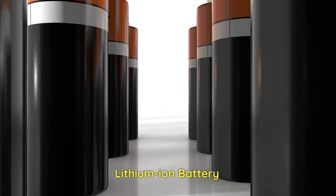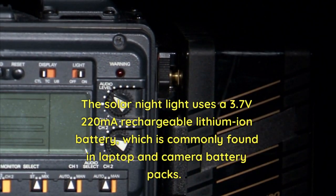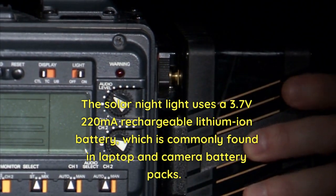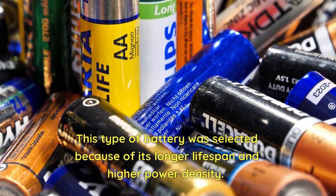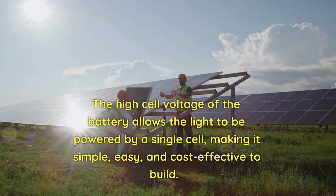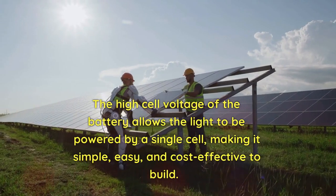Lithium-ion battery. The solar night light uses a 3.7 V, 220 mAh rechargeable lithium-ion battery, which is commonly found in laptop and camera battery packs. This type of battery was selected because of its longer lifespan and higher power density. The high cell voltage of the battery allows the light to be powered by a single cell, making it simple, easy, and cost-effective to build.